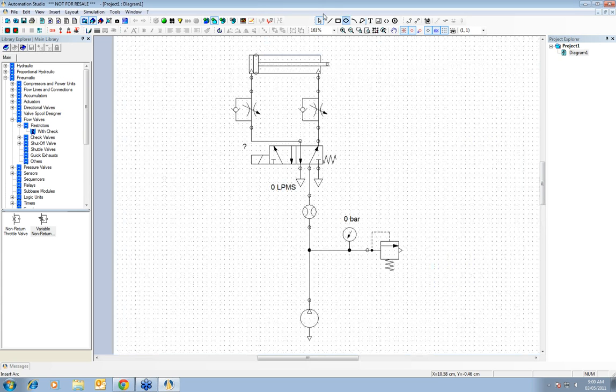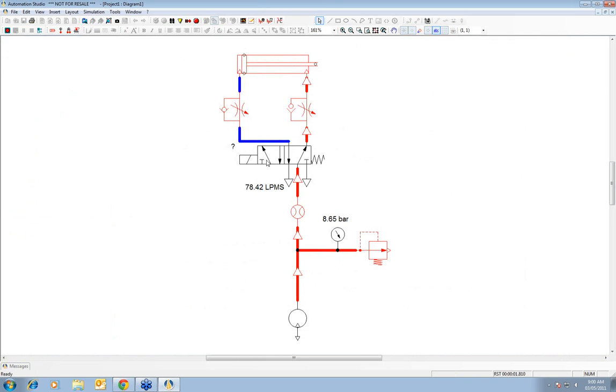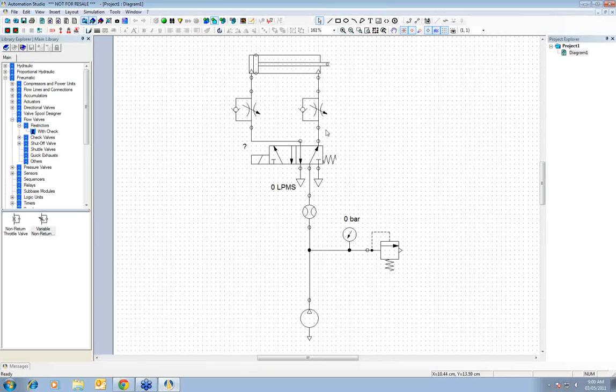So now same thing here. If you want to launch the simulation, no problem. You simply have to launch the simulation. If you want to use a circuit, you simply have to click directly on the valve. Now this one has a solenoid. As you can see, there's a question mark. We're going to fill this one in the next exercise. So this one is indicating that right now it has not been assigned to any solenoid, so that's why we have to manually shift the valve by overriding the valve by clicking directly into the spool position. Again, if you want to release that forced state, you have to click on either of the commands that you have on the side. Okay? Good.